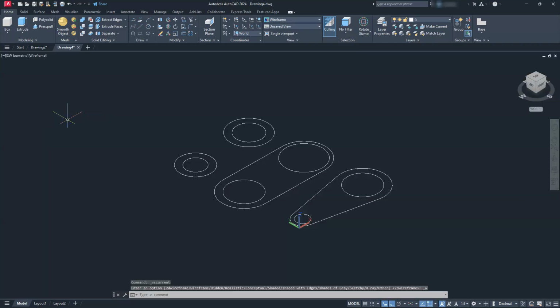And the next thing I need to do is remember that these are 3-dimensional parts. You're always going to have to verify and make sure that these are joined together. And I know when I created these pieces, they are not joined together. You can see that they're each individual pieces. Now I can use the join command, just J, enter.